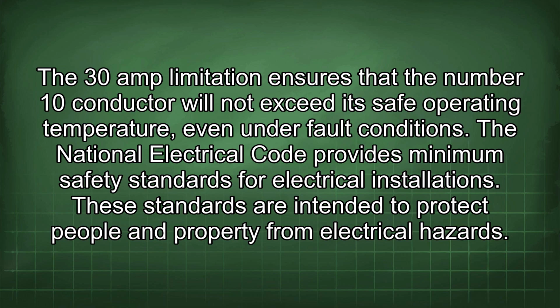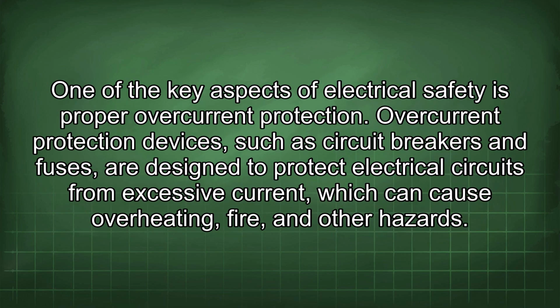The 30 amp limitation ensures that the number 10 conductor will not exceed its safe operating temperature even under fault conditions. The National Electrical Code provides minimum safety standards for electrical installations. These standards are intended to protect people and property from electrical hazards. One of the key aspects of electrical safety is proper overcurrent protection. Overcurrent protection devices, such as circuit breakers and fuses, are designed to protect electrical circuits from excessive current, which can cause overheating, fire, and other hazards.